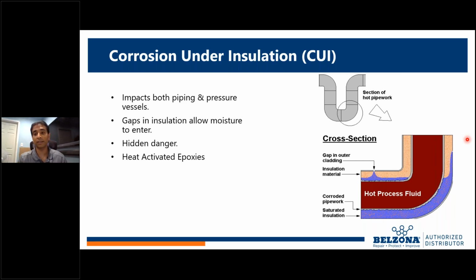However, it comes with a big downside. And that is when you put the insulation on, there's generally an aluminum cladding that goes over top of it that has caulk that's used to seal all of its joints. Well, once you go through a couple hot cold cycles, that caulk breaks, water enters, and now you've got water trapped inside of that insulation. It's got nowhere to go.